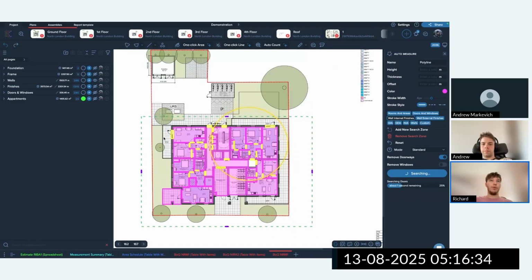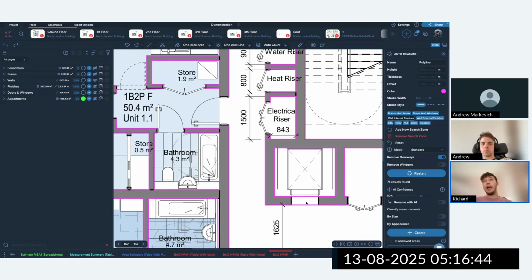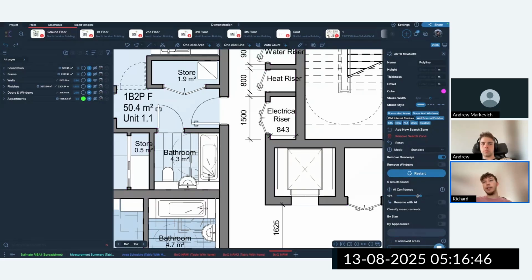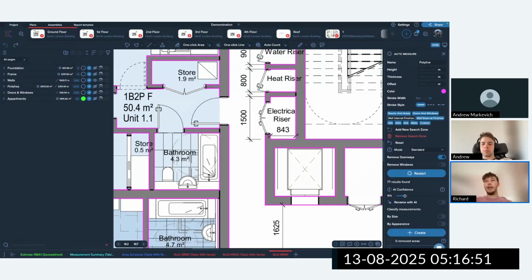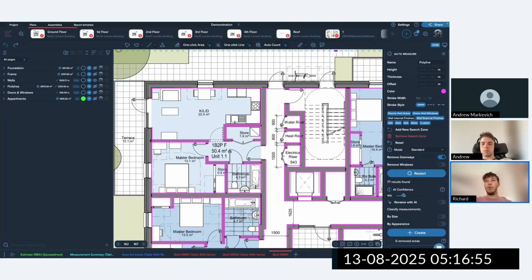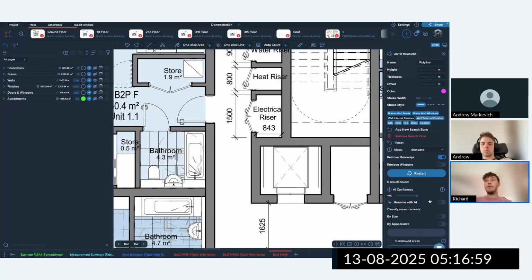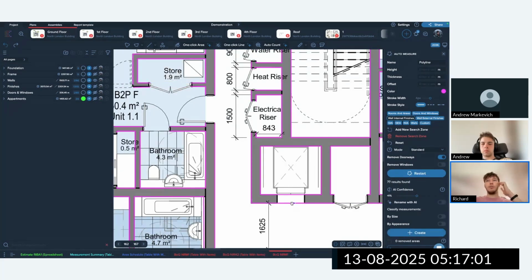So we launch it from the beginning, but now you see all these doorways were removed. So for sure, in some cases, Creo can miss some doorway, like you can see here. And this is a perfect example where you may need some AI confidence improvement, because if you make it less, Creo will find this particular doorway, and you then can get this removed. If you want to remove this manually, Creo has all the necessary tools to do it.